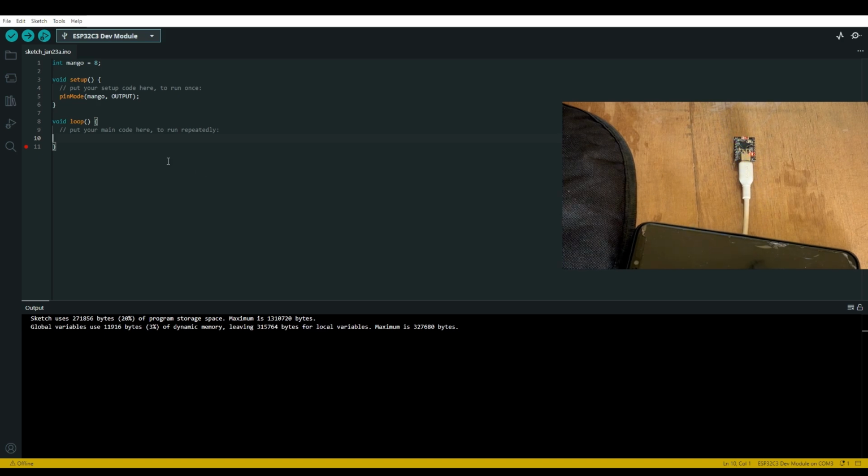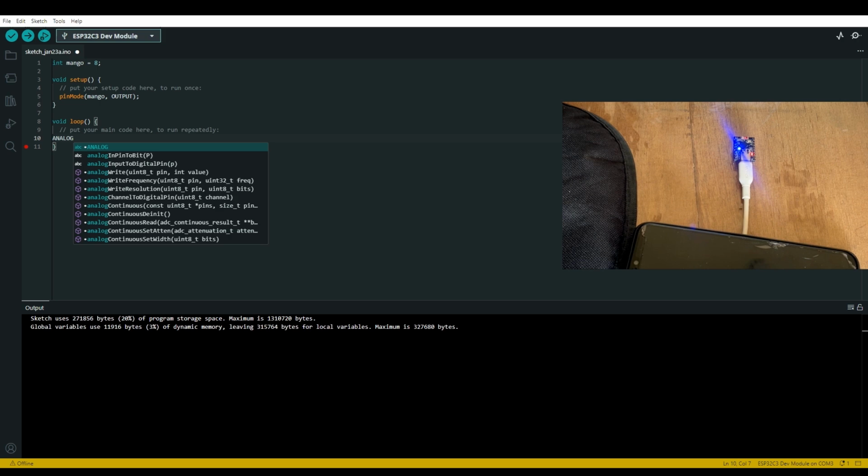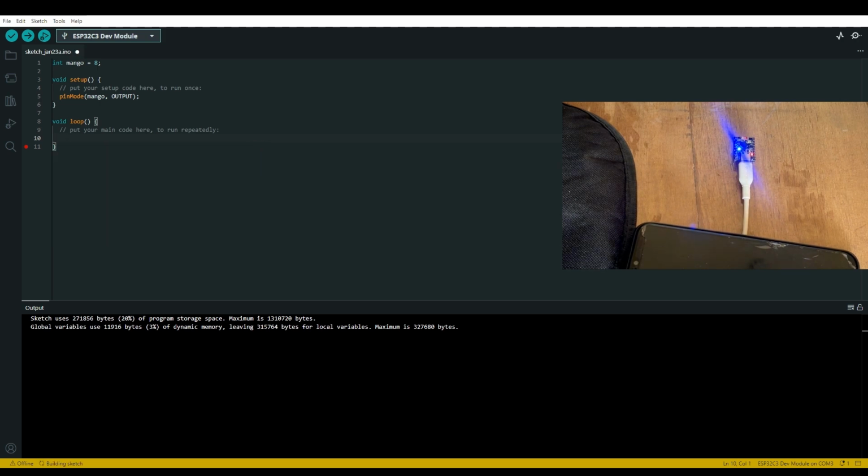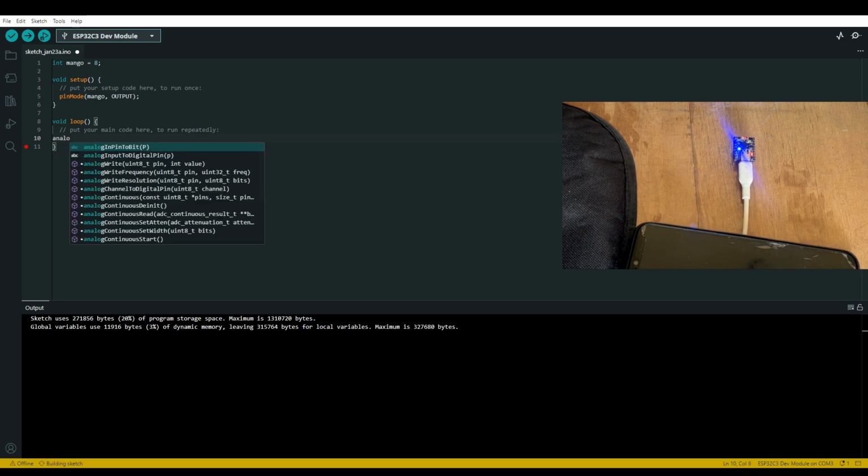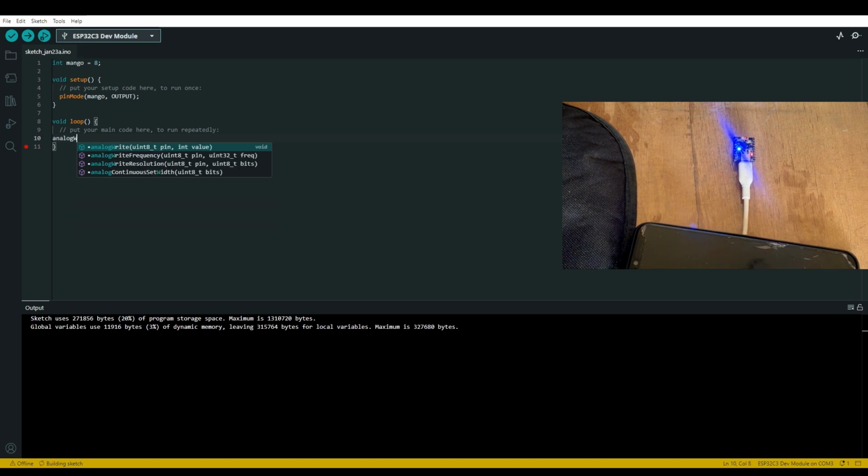So what we're going to do right here is analog write. In the first video I made, we used digital write. You call the pin's variable, and then you set the value to high or to low. But today we're going to be using analog write. So we're going to write analog, caps lock, Write. And then we are going to be using the pin.